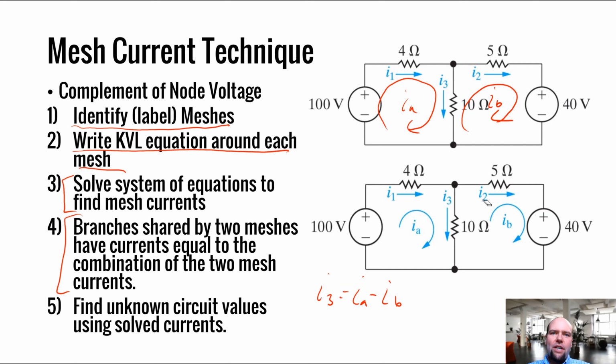And is that really the way it works? Do we actually have, in this wire here, half the wire with a current flowing this way and the other half with a current flowing this way? No. We don't actually have these two currents swirling in opposite directions, but mathematically it works out the same. Why does it work out the same? If we think about the current swirling, we have this I3 equals IA minus IB. Why does the math work out?